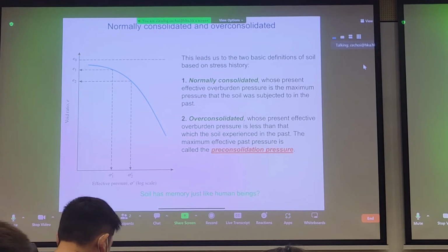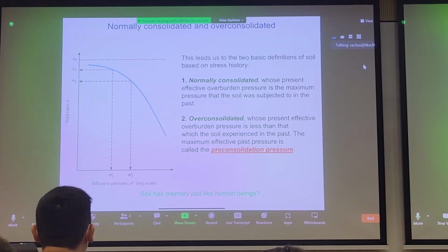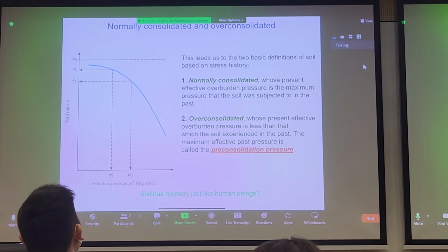So in fact, we're applying a load that's much higher than the soil is actually experiencing, because it's undrained. Well, under that circumstance, we can say it's under-consolidated somehow. But you rarely see a term like that. It's quite a niche case. But in general, we usually just say normal or over-consolidated. But let's take a look at a few examples.